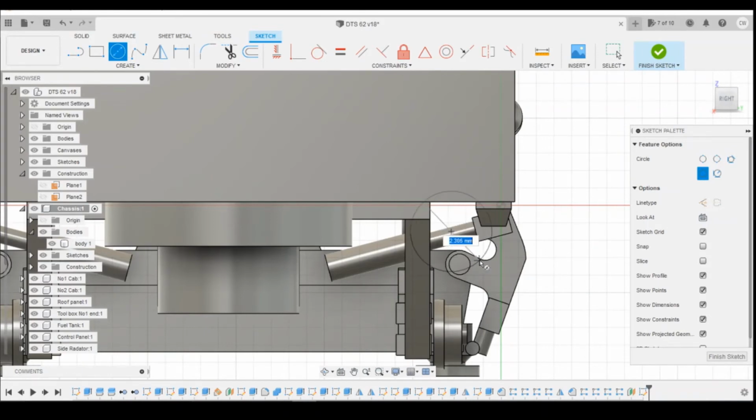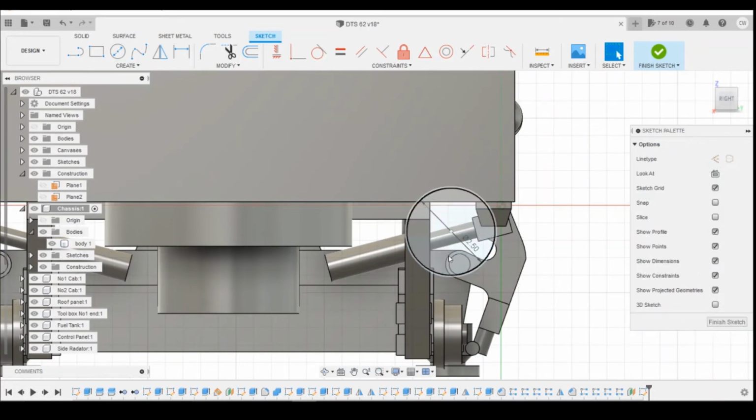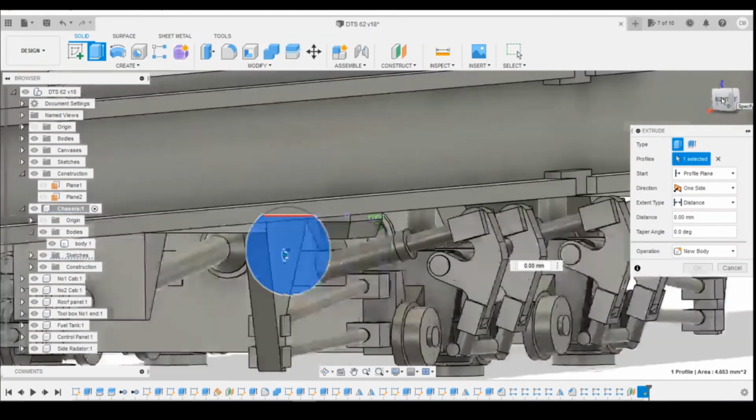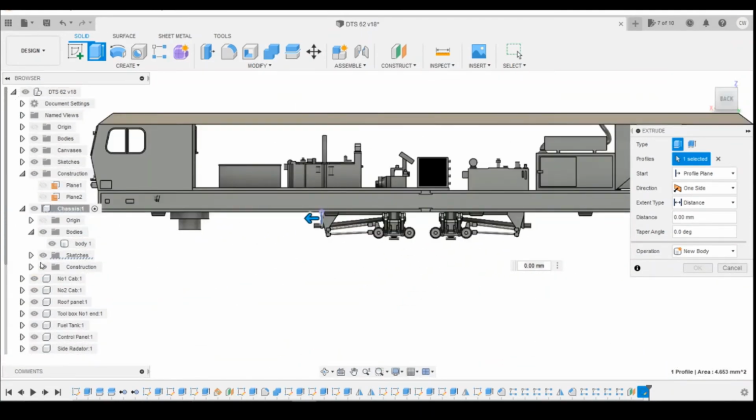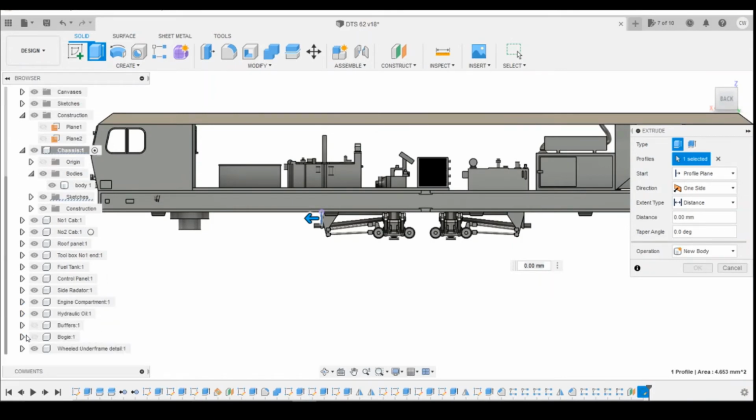Okay, I'm going to go for maybe 2.5mm tank. I'll have a look at that and maybe change it in a minute, depending on how it looks once I've extruded it. Distance there, I'm going to go for 1mm, so there's only 0.25 that's sitting into the bodywork there. Distance from the side of the unit, I'm going to go for 1.8mm. Okay, we can extrude this, and we've got to be careful that we don't get too close to the bogey as well. That's one thing we've got to consider. If we just turn that on, yeah, we've got plenty of room there.